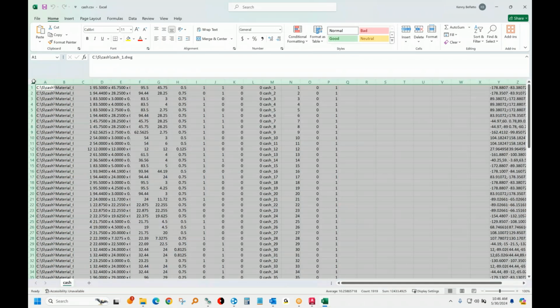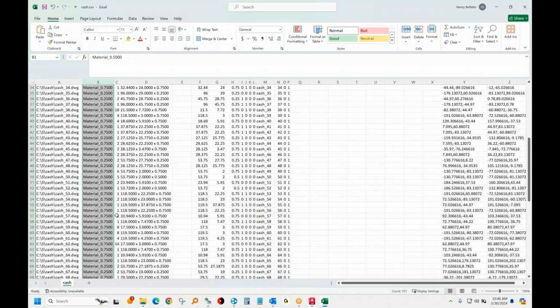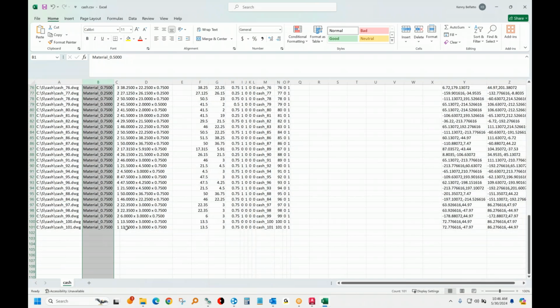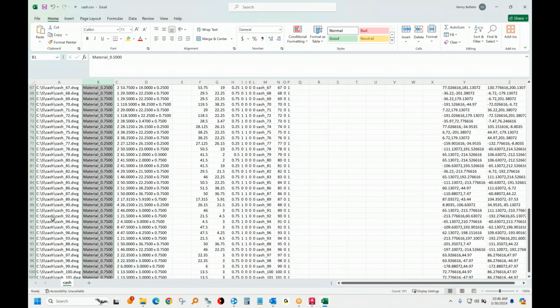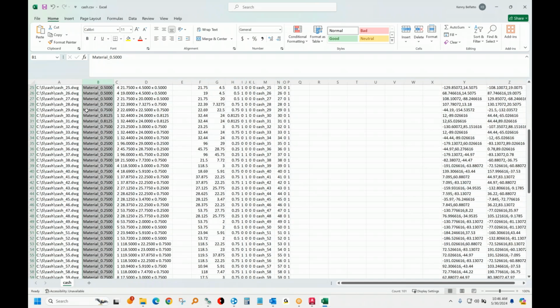Okay, so here you've got the cut list. You've got the name of the part. There's the material. There's the quantity. So it did see 12 of these parts, 4 of these, 18 of those, right? You got different materials. There's 101 parts with these different quantities. Most are on 3/4, some are in 1/4 inch, some are in half. There's the panel dimensions. That's the minimum size panel to cut these parts.